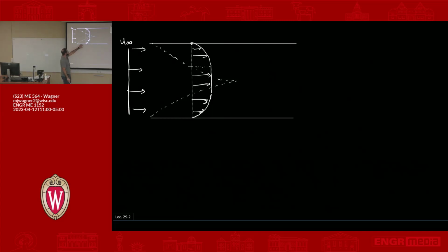One question is, we have a slower velocity here because of the no slip condition, right? The velocity near the plate has slowed down. So the velocity in the middle, is that U infinity or something else? It's going to be faster. It has to be faster, right? Because you've forced stuff near the edge to go slower. You have a constricted volume. Therefore, the stuff in the middle has to go faster to compensate for that. So as you go along, the core kind of accelerates a little bit. And that becomes important when we're talking about conservation of momentum.